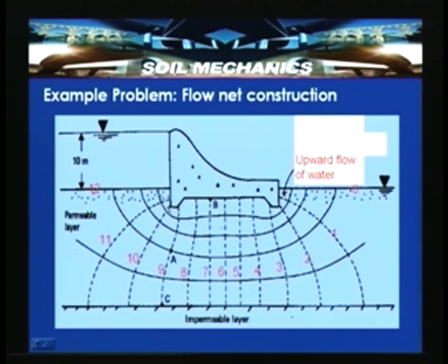So, when the flow is taking place here, the effective stress increases here. When the flow is taking place at this particular point, the effective stress decreases. So, that actually creates upward flow of water, particularly at the tips of these structures, which can create piping failure and all. Then we have methods for estimating these considerations and then arriving at stabilizing these problems.